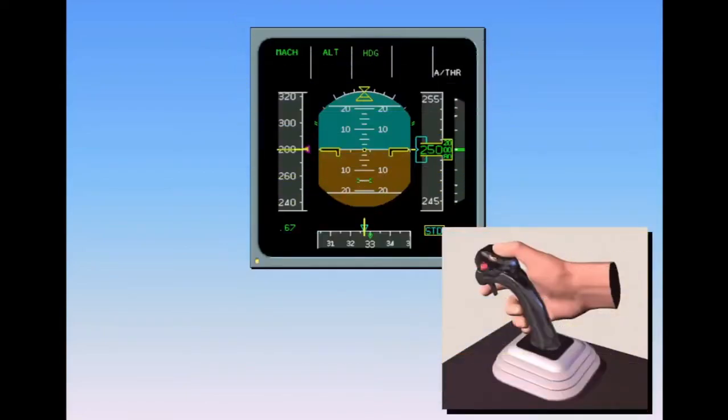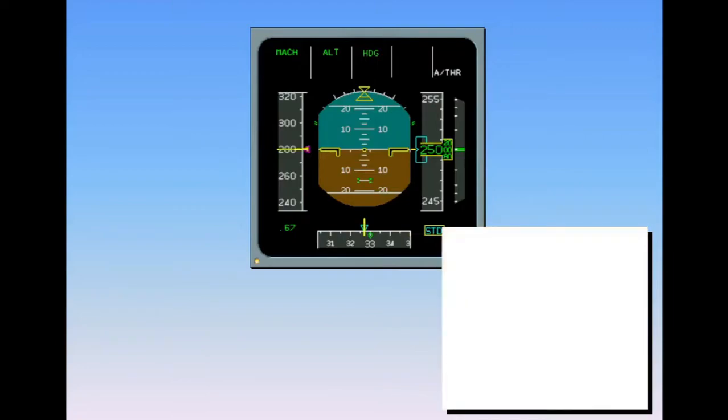In flight mode, if you wish to execute, for example, a left turn, you set the required attitude and then return the side stick to neutral. The neutral side stick position demands 0 rates of pitch and roll. The flight control computers will maintain the set attitude until you use the side stick to demand an attitude change.